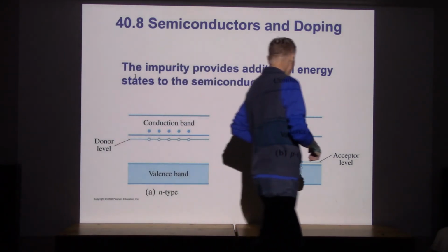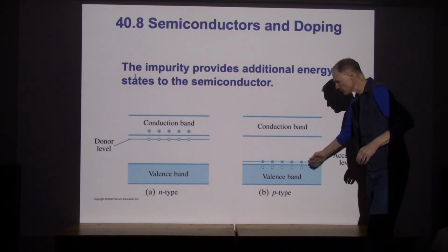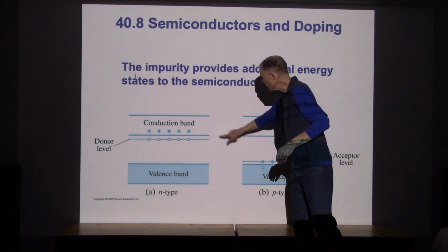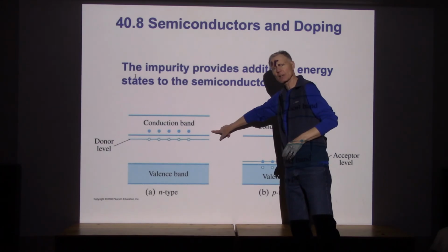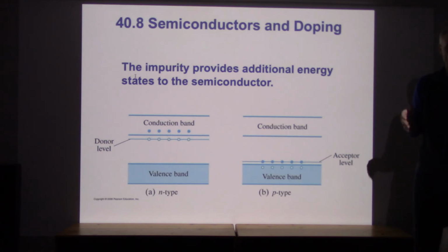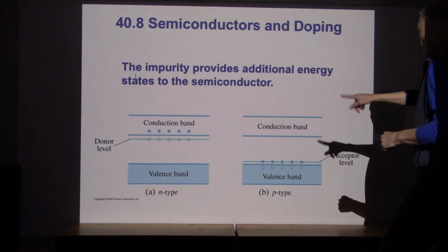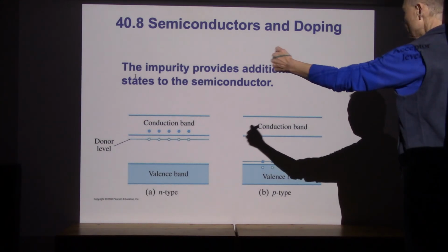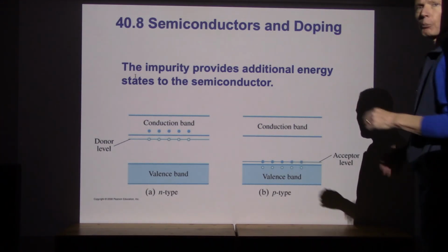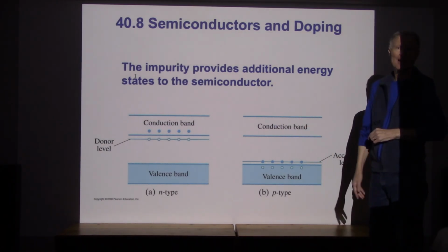But when the electrons come in through the p-type, they end up in these lower energy states. In order to conduct, they would need to jump up into one of these conduction states. That doesn't happen. Now, if we put a diode in a circuit and drive enough voltage, we can force the issue. But under normal operating conditions, diodes are designed with these properties in mind: going from N to P for the electrons, no problem. Going from P back to N for the electrons, that just doesn't happen.